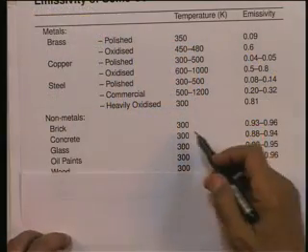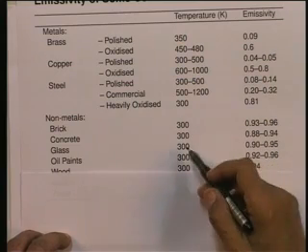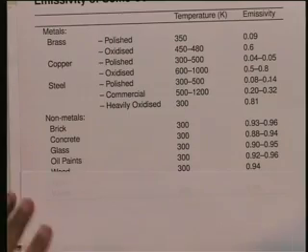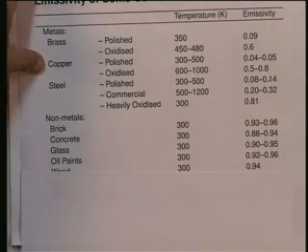That is a second comment about emissivity values. Again I repeat, if you want precise values, you need to go to handbooks, because emissivity will also be a function of temperature. Here I have given the value at a particular temperature. It will be a weak function of temperature, not varying that strongly, but nevertheless a function of temperature.